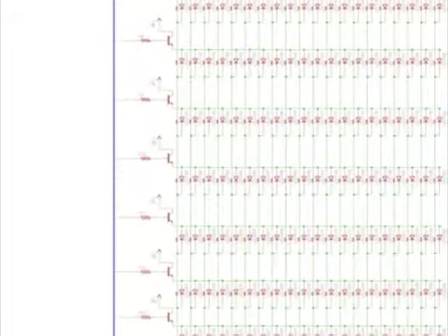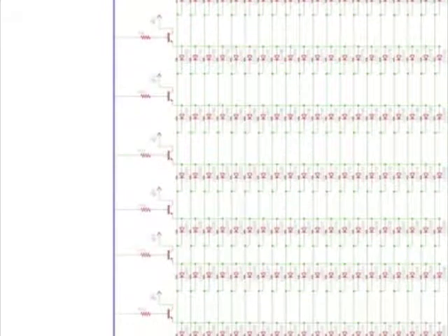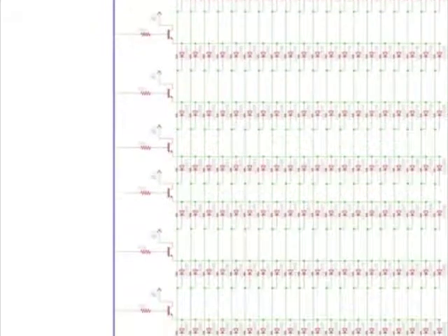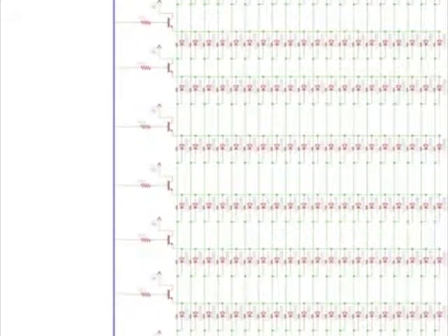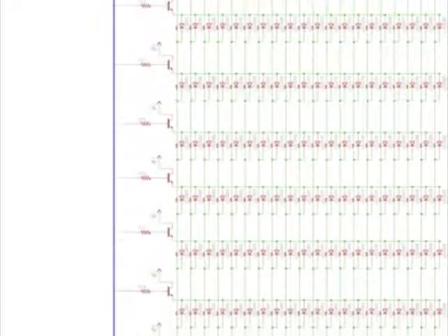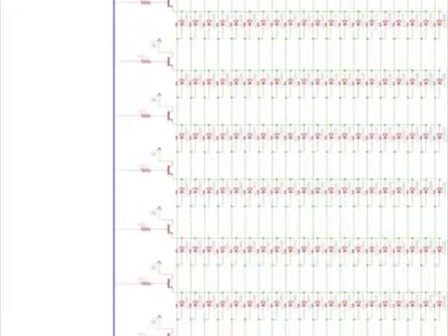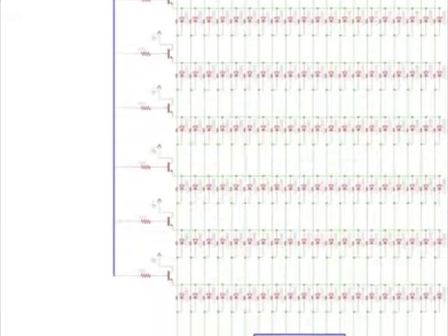The chip will control a series of serial in, parallel out shift registers. The rows will be cycled through sequentially, while the columns will be serially loaded and outputted in parallel to correspond with the row currently powered. We attempted to keep all sections fairly modular to allow for fixes and upgrades.